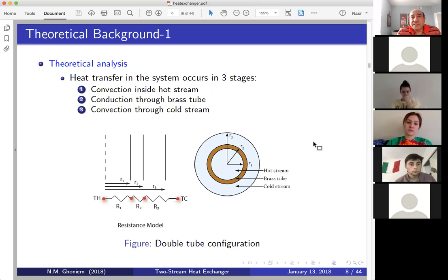And as we will see, the NTU is an experimentally measured quantity, and it involves the heat transfer coefficients. So by definition, it's going to have the conductance times the area divided by Cmin. That's the NTU. So the bottom line here is that we know the areas, we know Cmin because we measured it, but we don't know the conductance U, capital U.